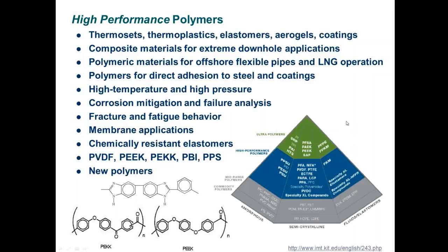Elastomers, FKM, etc. Fluorinated systems. These polymer materials are being used increasingly to replace metallic parts, and also rubber, HNBR, NBR. These are very commonly found in blowout preventers, packers, hoses. They are used for the longest time, but actually need updating. So there are many choices. The question is, when do you start introducing these high-performance materials more commonly, and reducing in price and improving their performance?